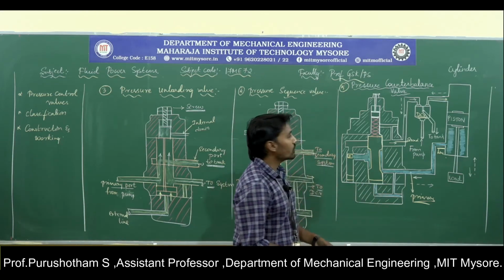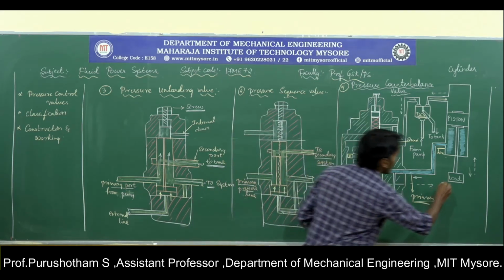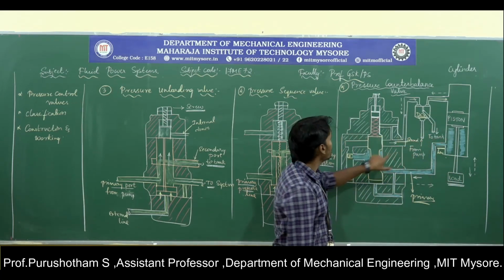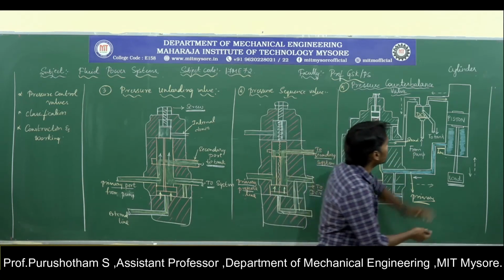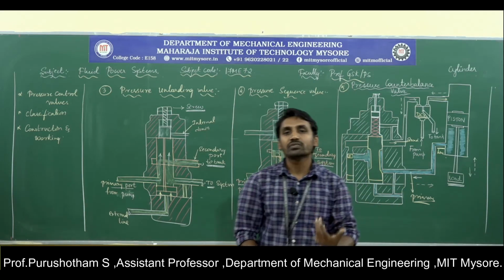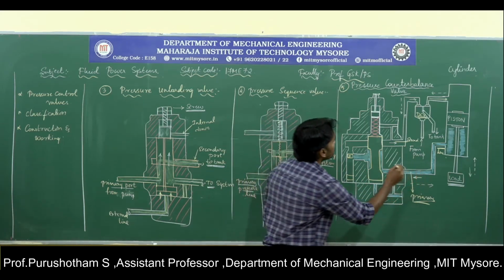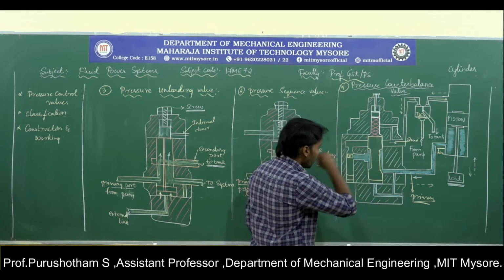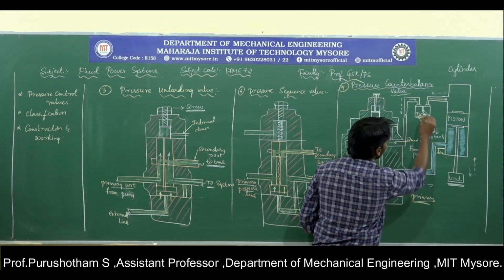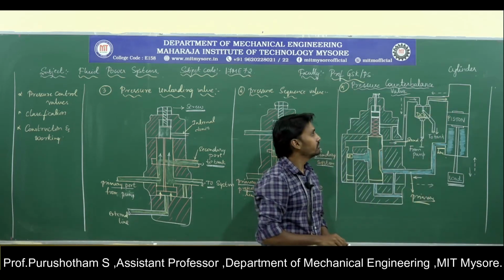So when used in vertical cylinders, the load descending has to be smooth. If you are not using this counterbalance valve, what will happen? The motion is very odd, which is going to damage the cylinder and increase the pressure, which will cause damage to other components in the hydraulic system. So for this we are going to use the counterbalance valve. When the pump discharges the fluid, the direction control valve transfers it to the upper end of the cylinder.